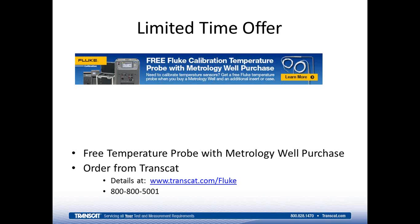If a probe is handled properly and it's not subjected to a really high range of temperatures at its maximum, it's likely that it isn't going to change a whole lot. But there's absolutely no way for anybody to guarantee that it won't. So we always have to consider that there's some level of risk associated with that. But lower temperature ranges and handling them properly definitely helps. We would recommend that you evaluate your situation specifically to determine how often you should calibrate it.